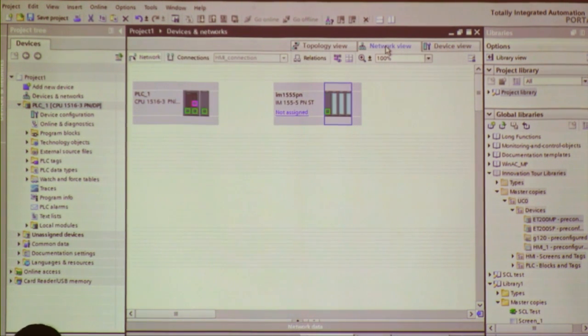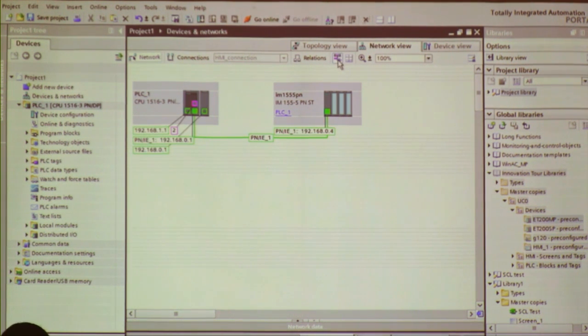So now I can come over here. What did I do before? Select my Ethernet port, drag and drop that to there. So now that's assigned. Okay. So it's on the subnet, it's assigned. Then I'll take the next, and you can see here, it took the Profinet address, or the IP address, that it was put into the library with. So it remembered that when I pulled it back out. Okay? So when I download this, I shouldn't have any problems.